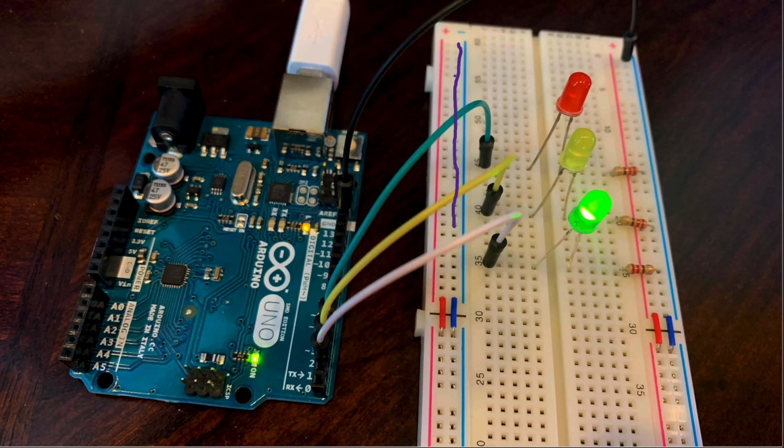If one of them is connected to the current, all these lines together will be connected to the current, this line as well. They will stop from here, they will come up to here and stop. So you can see in this breadboard what this person has done is they have connected these two with these two. You can see the wire over here which is a pin, which makes all these lines connect. So all these lines are connected, and the same thing has been repeated on this side as well.